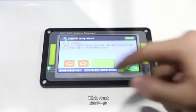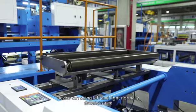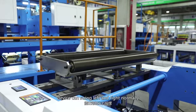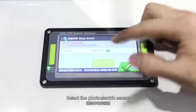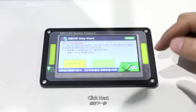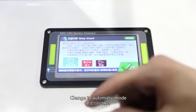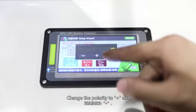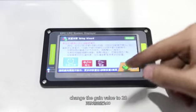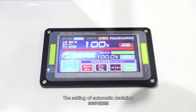Click Next. Click the left and right arrows and the correction device can swing left and right normally. Click Next. Select the photoelectric sensor. Click Next. Click Next. Change to automatic mode. Change the polarity to add and change gain value to 20. Double-click to return. The setting of automatic deviation correction system is completed.